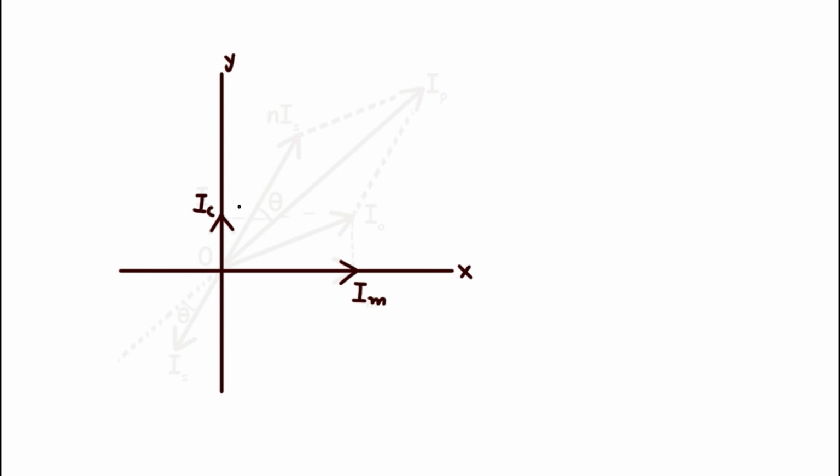So when we connect the CT in series with the line, and the circuit current flows through the primary of the CT, that current will also have to contribute the magnetizing current and the core loss current. The vector sum of these two currents is I0. I0 is called the excitation current of the current transformer. This is nothing but the vector sum of IM and IC,